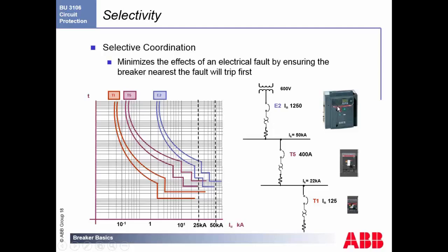because when you do take out the main breaker, you are shutting power to all the equipment down the line from there. So you can have several different engines, turbines, conveyor belts, what have you, coming off of that breaker. You don't want to stop 5 lines because of a fault on one. So you would choose lower breakers and put them closer to the load so that if one conveyor belt has an issue, only that conveyor belt will pop.